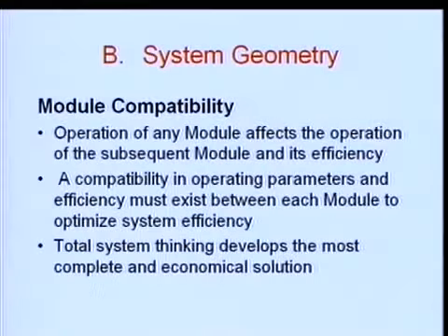Probability of removal is what is the efficiency? So how are you going to remove them, and what will be the probability? Now in screens there may be a higher probability of removing rigid stuff, but in a cleaner the higher probability is based on specific density, and hence the probability in the two cases would be different for different contamination. Then of course the residence time.